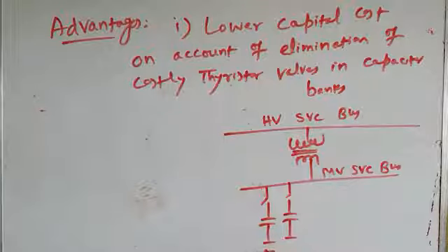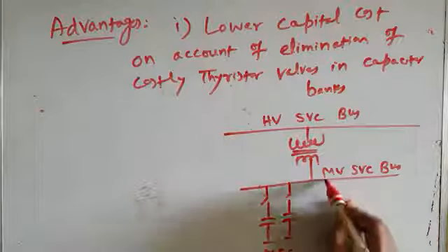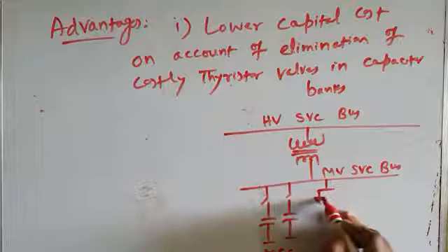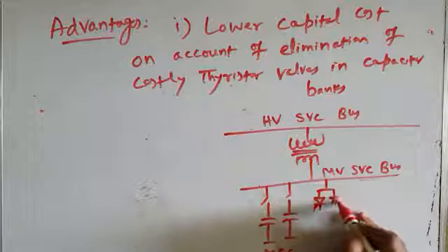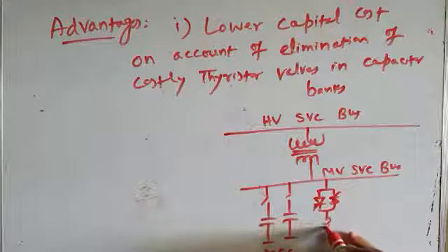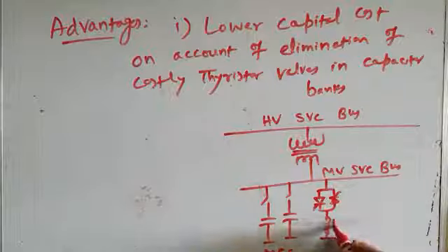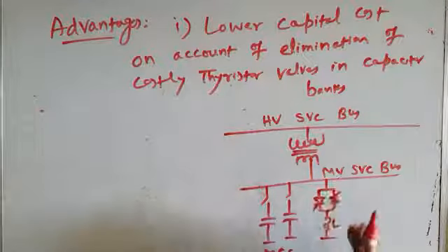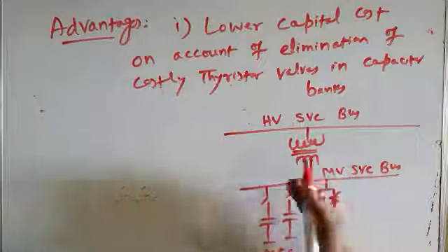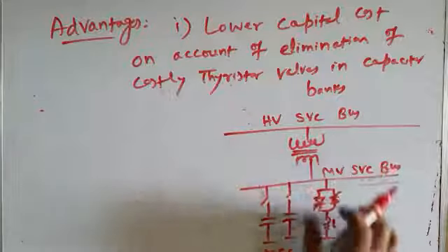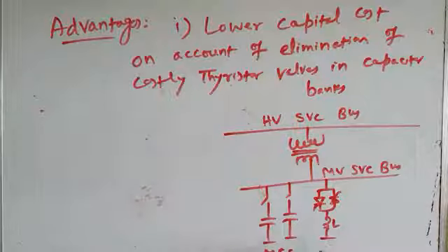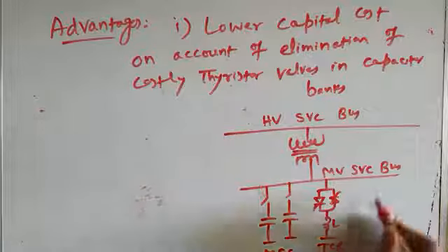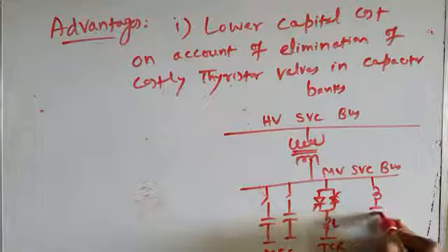These are MSCs, and we have the thyristor controlled reactor, TCR, which, let me tell you, is not a single TCR, it's a segmented TCR. One TCR and many TSRs are connected in parallel. Because of the non-availability of space, I am showing just one TCR, but actually it is a segmented TCR. So let me write TCR here, and then we have the harmonic filter like this.